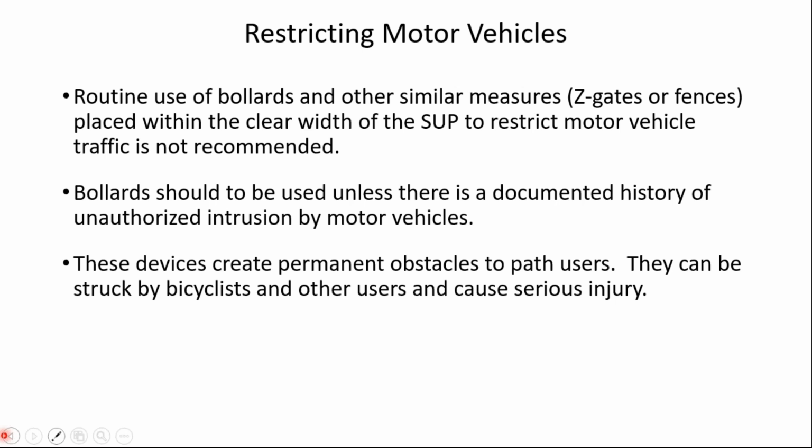Generally, these are not recommended, although I know they're widely used, but bollards are a fixed object hazard to bicyclists, and also to pedestrians. In fact, the new AASHTO bike guide, as some of you may be aware, talks about bollards and their adverse consequences in several locations, but it also talks about how to use them, if you're going to, to minimize some of these adverse consequences.